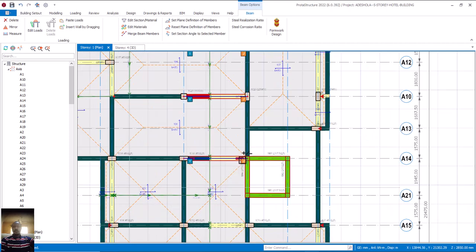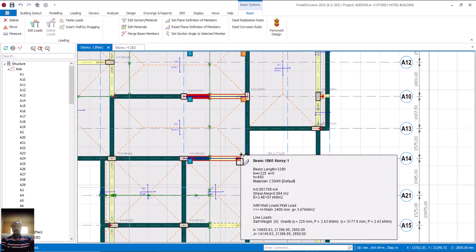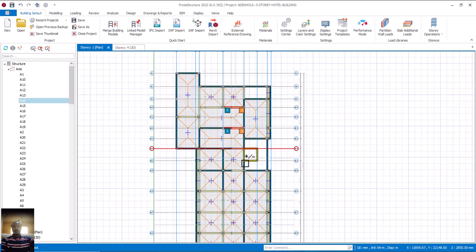Now, if you look at this one also, this one is coming to rest on what? On my shear wall, and the shear wall is not meant to what? To carry moment. Is that okay? So I also hinge this place. Is that okay? My J, I also hinge that place.